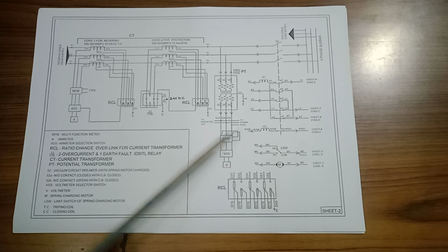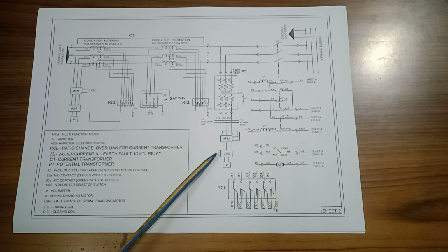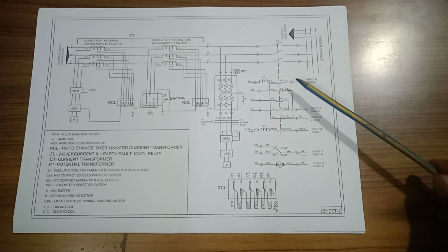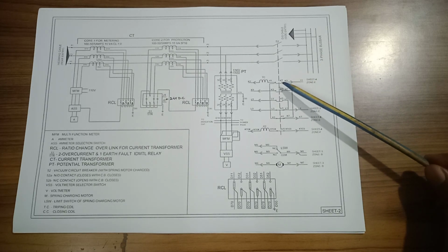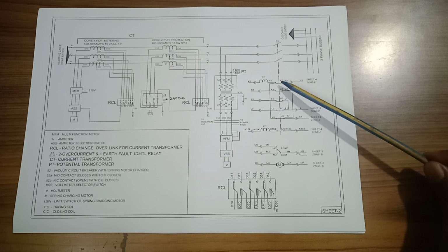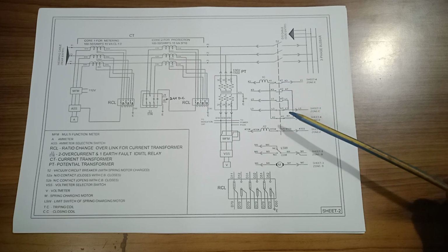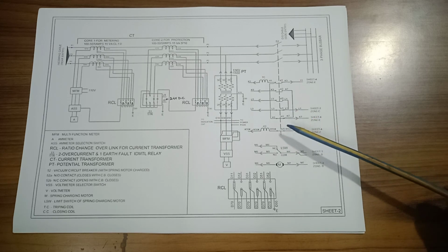Here is the auxiliary supply 110 volt, and this is the voltage selector switch that goes to the voltmeter. Here is the ammeter selector switch that goes to the ammeter. Here 52 means the circuit breaker. Here 52A by 1, 52A by 2, 52A by 3 are the circuit breaker auxiliary NO contacts. Similarly, B by 1, B by 2, B by 3